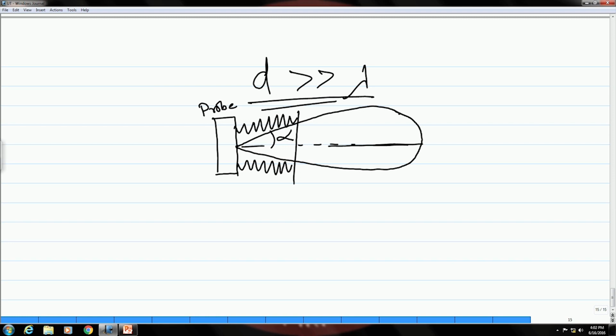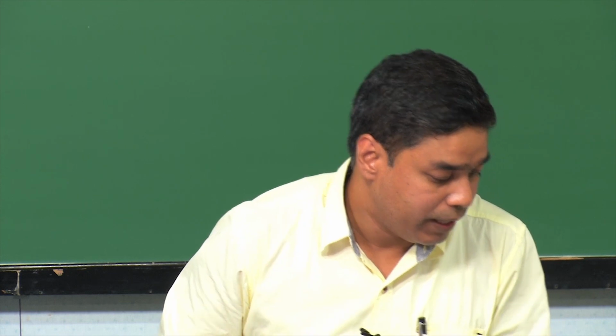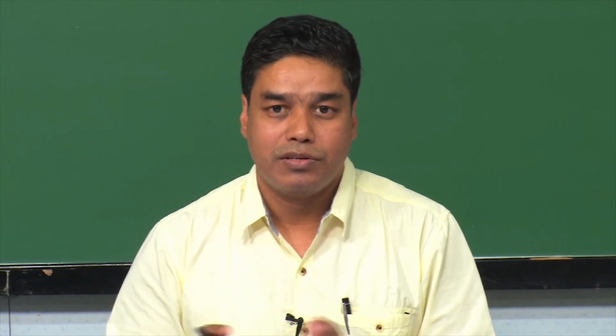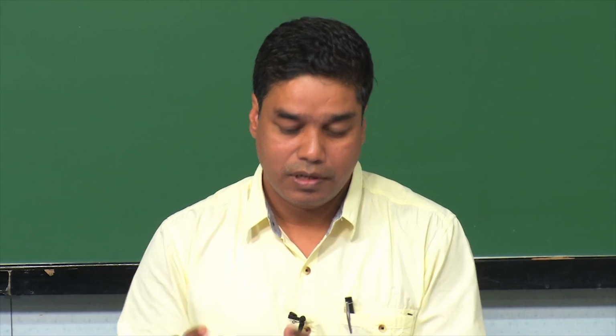Close to the transducer there will be a lot of fluctuations in the intensity, and as it goes away from the transducer, the beam becomes more uniform. These fluctuations will die down and the beam will take up a more uniform form. So, there are two regions based upon that, depending on whether you have fluctuations or not.